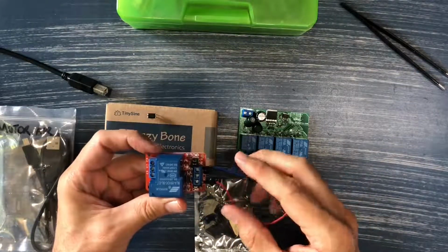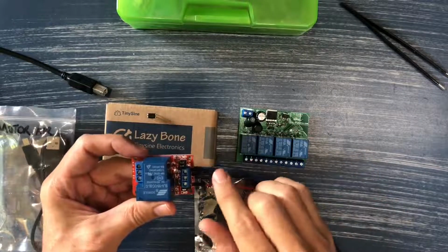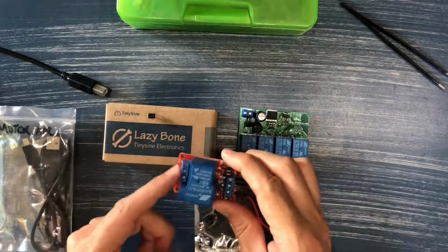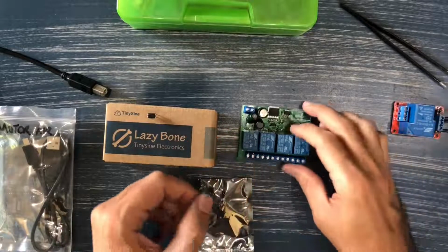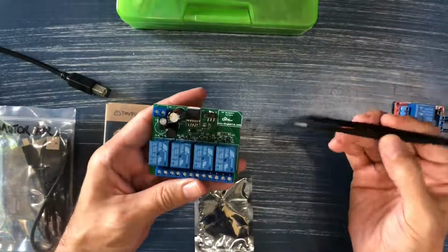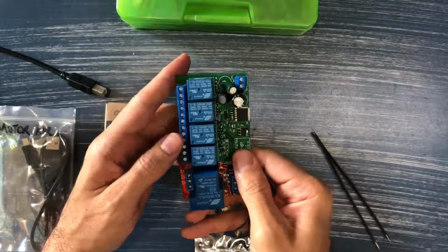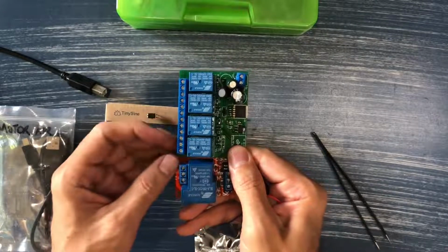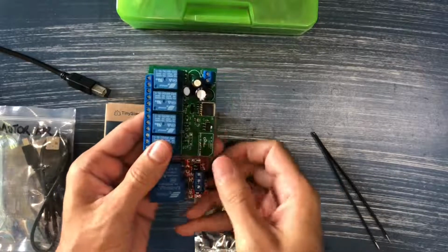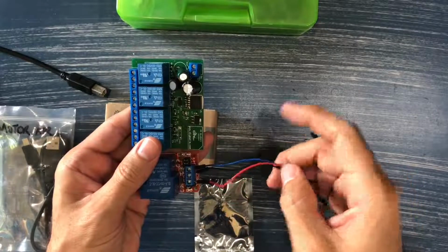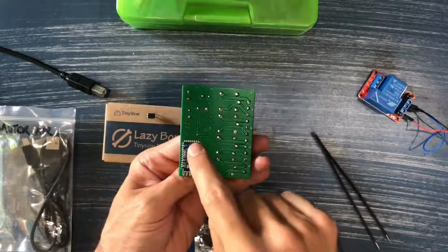So in this case, we saw the relay, and it had a low side, which was the 5-volt DC, and it also had the high side over here, which is where you connect it to the object you want to control, the actuator. In this case, the first difference is that there's actually 4 relays instead of just 1. But if we line this up, the high side is over here, where you connect the lamp or the motor. The low side, which is the one you're going to control digitally, in this case has no cables, as you can see. It's over here.